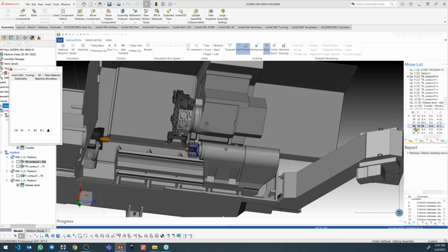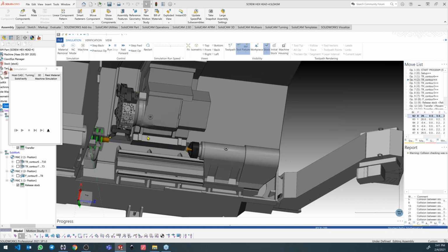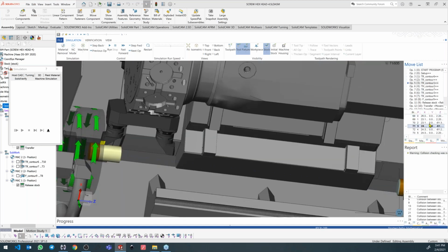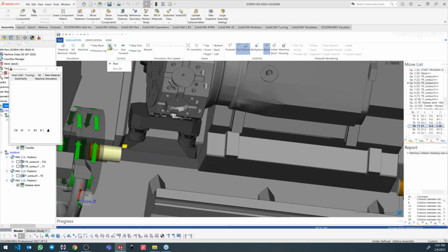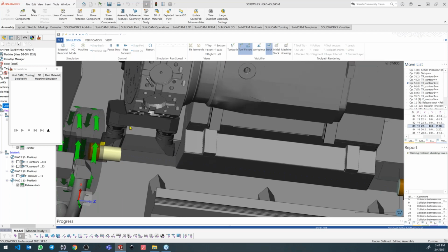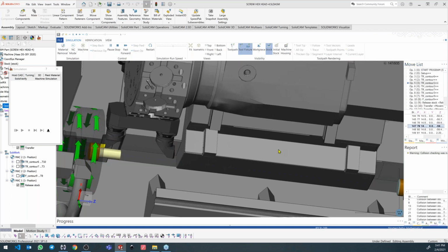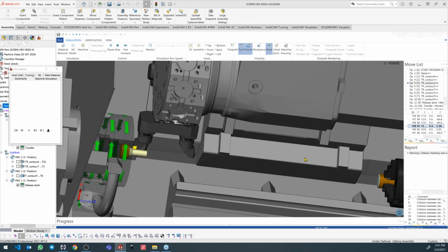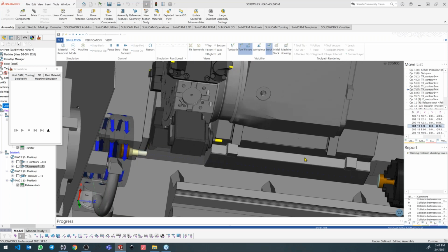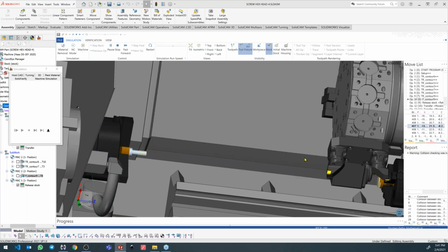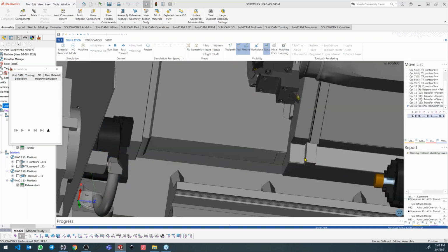When it's finished here, it will move to the back to the main spindle. Still with the same tool holder and machine here. You can see the machining, and when it finishes here, it will come back and finish work on the back spindle. This kind of machining is of course much more productive than regularly moving from spindle, making all operations on the main spindle and moving to the back.